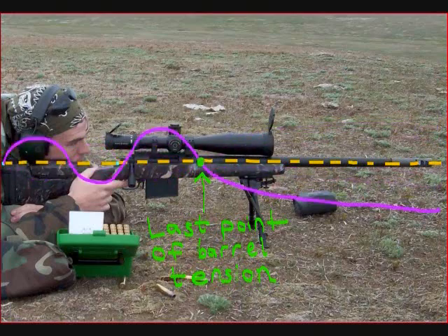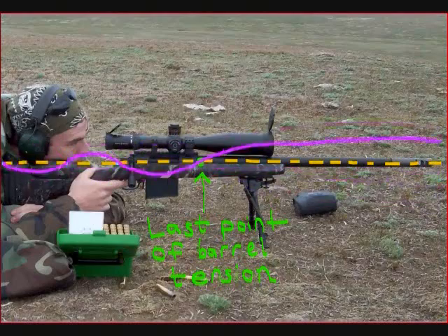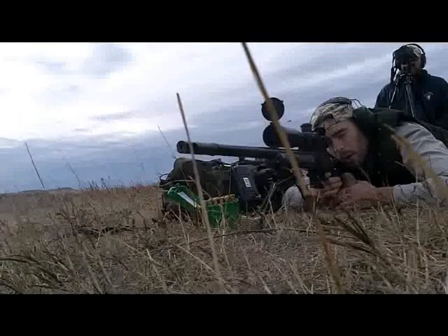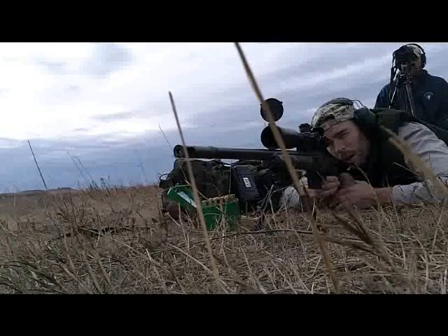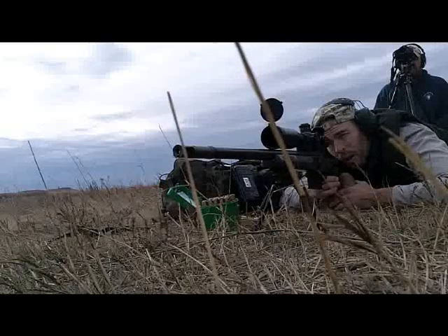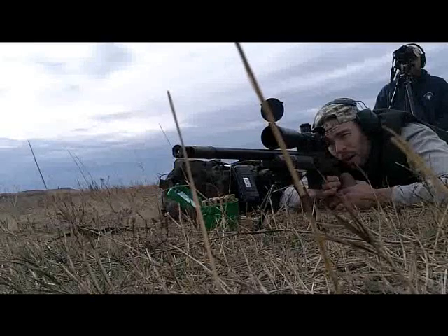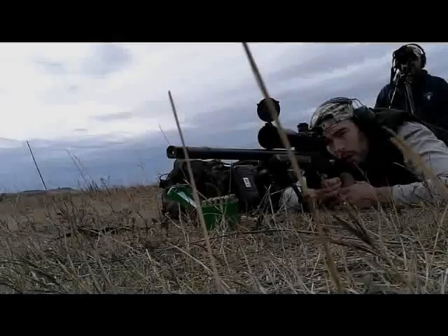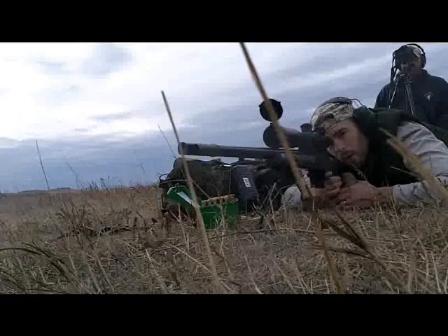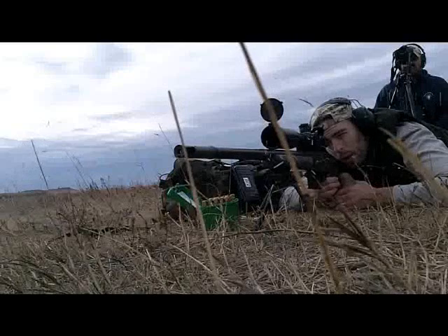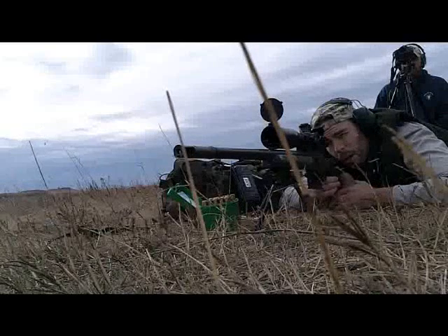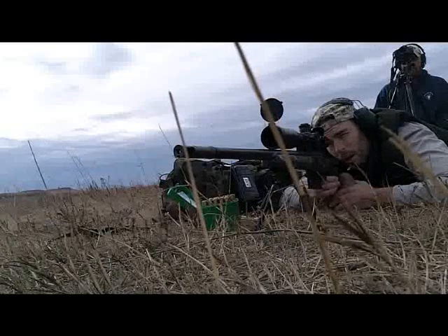And that's one way of taming that down. And that does two things. That reduces the amplitude of the antinode regions at the muzzle. So your vibrations, the actual physical distance your muzzle is flapping back and forth, will be reduced, although the frequency, the speed of the flapping, will be increased. That's just the physics if you look at harmonic waves. So that's one thing you can do to reduce the amplitude, so that the point of impact shift will be just smaller, okay?